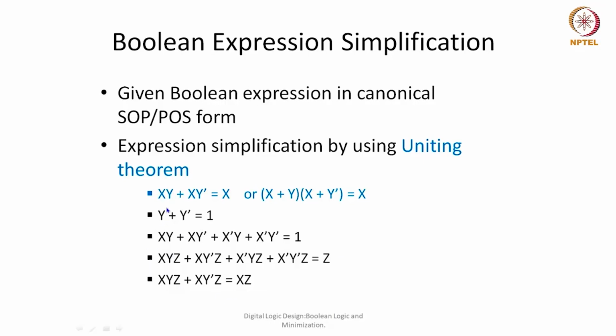Now the uniting theorem says that xy plus xy dash is equal to x, and for product of sum it is (x plus y) into (x plus y dash) equal to x. So this uniting theorem can be applied multiple times, again and again, to reach a final solution.